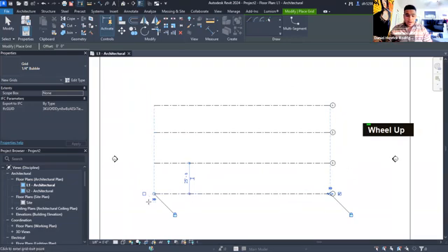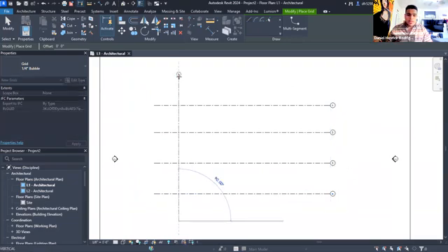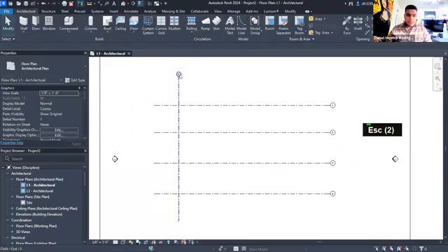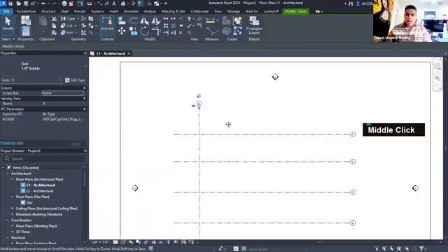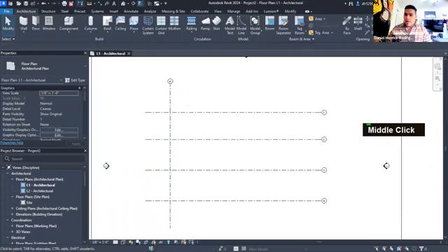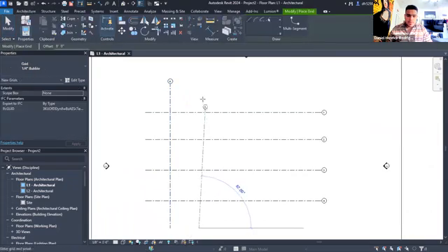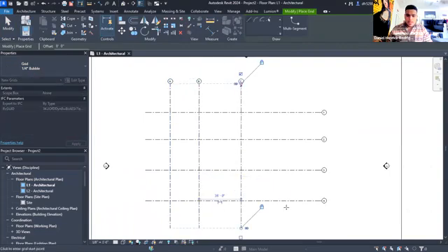Now, Revit does that automatically. So when we put this one down, it's going to be 5. What we can do is click on here and make it A. And as soon as we make one A, Revit already knows that the next ones are not going to be numbers, and it's going to go ahead and give us B, C, and D.